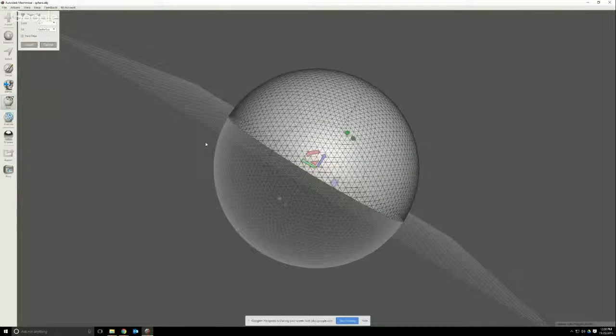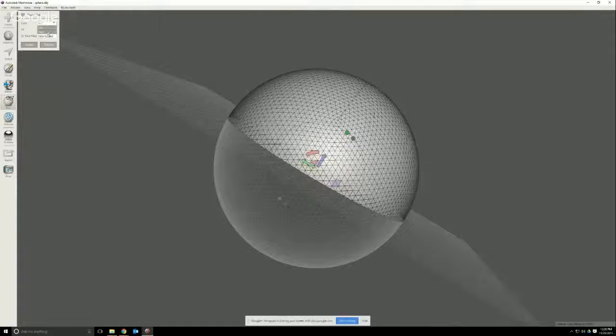So instead of cut, I'm going to slice. What slice does is it cuts a line through, but it doesn't discard the other side. But right here with the type of fill, delete refine will actually create a half sphere here and a half sphere here with two sides that are absolutely 100% touching. That's not what I want.